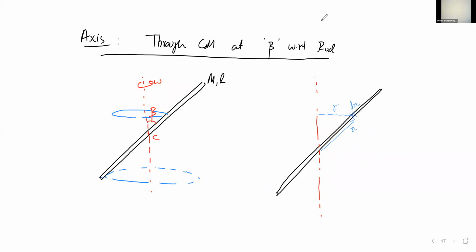So this also explains the importance of the quantity r in the case of moment of inertia. It is the position of a particle with respect to the axis of rotation, that means the perpendicular distance from the axis of rotation at which the particle lies. As this body rotates with omega, this particular particle is describing a circle with radius r. So its instantaneous speed will be r omega. So its kinetic energy will be half dm into r square omega square. So the whole thing's kinetic energy is half I omega square. So how will we calculate I? Again by integration of r squared dm.